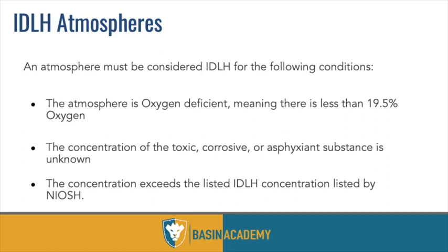It's nice to be optimistic, and I'm kind of an optimistic guy, but when it comes to H2S, there is no room for optimism. It's all bad all the time. However, and we're going to get into this in a little bit, there is a way to prevent exposure, and we do it every day. This is part of our work scope, so there is a way to prevent exposure and potential harm to your body. So for both SO2 and H2S, again, the IDLH is 100 parts per million, so keep that in mind.